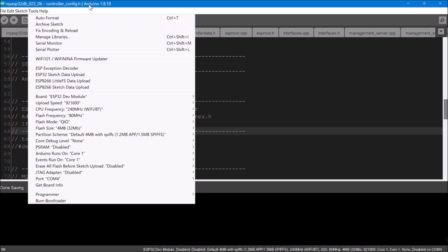You can't do that in Arduino 2.0, etc., because that's not supported. So you could only program the controller, but the problem then is because all those data files don't exist, the controller won't boot up properly. It'll recognise that those files aren't there, and it'll just go into a continuous reboot cycle.